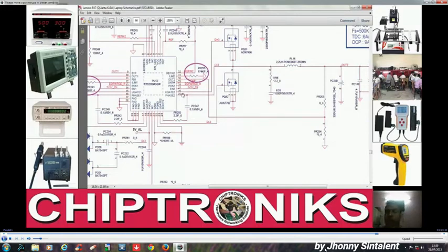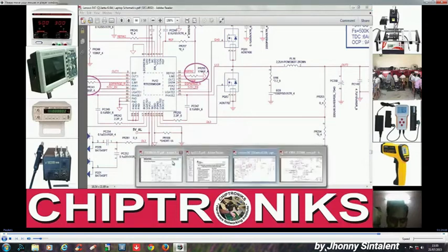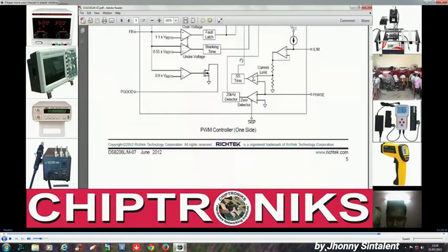So there are two pins. One is Vout, another is feedback. Vout is for providing internal feedback to the PWM inside this IC, and feedback is like, if we are not using feedback, then it will operate in fixed manner. If we are using feedback, it will work in adjustable fashion, right? Okay, so let's see the other pins.